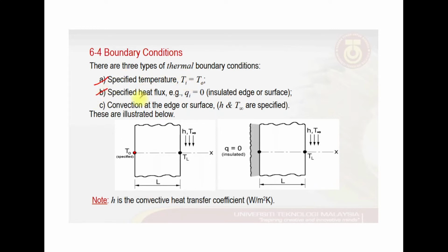B is known as the heat flux, and given by Q equal to 0, which means there is no heat flowing across this region or face. So here on the left face of my wall, this face is insulated.